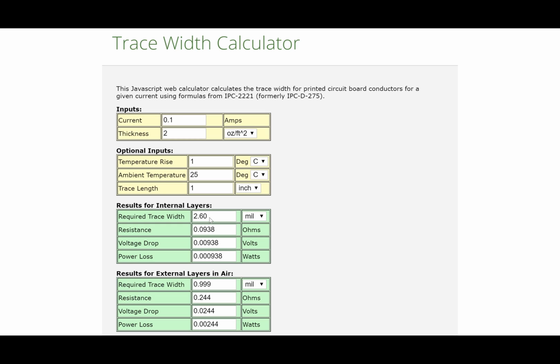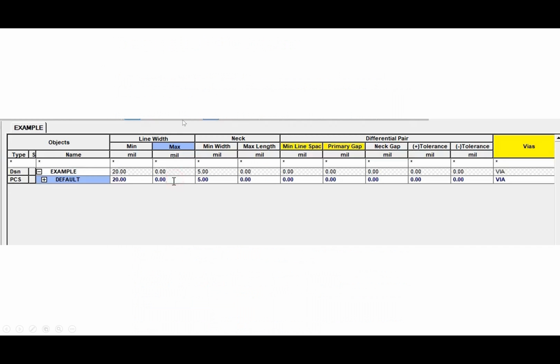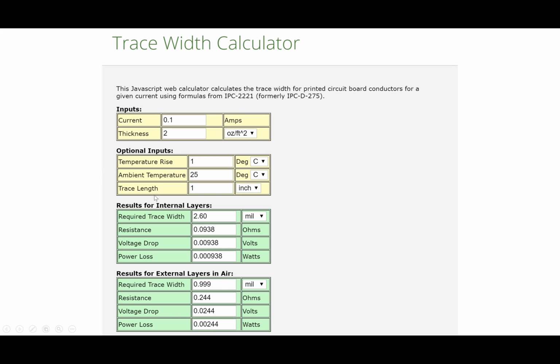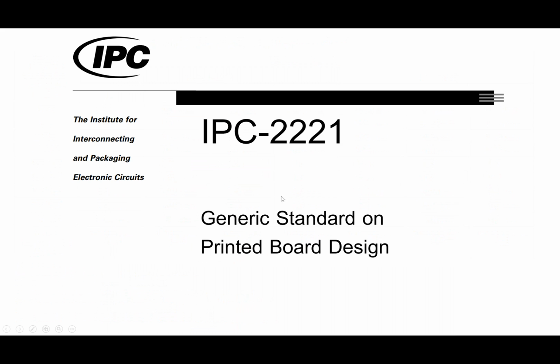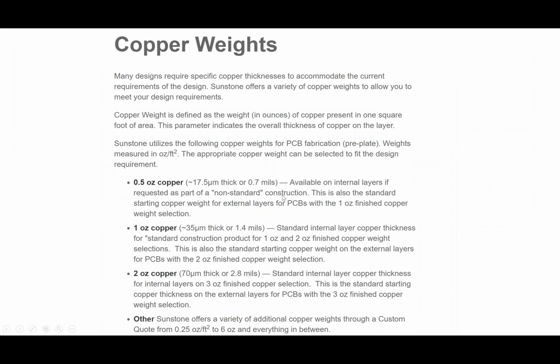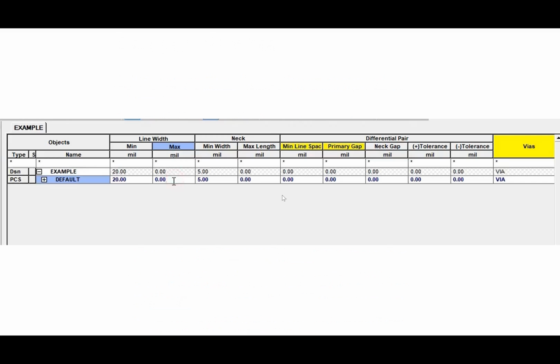His circuit is a power circuit. And typically if it's a power circuit, then we know the currents are going to be higher, and typically they're going to be thicker traces. So how we set these things in here ultimately gets decided by going through calculations like this, which are laid out in industry standards. Okay? So there's a lot for you guys to learn and to go through as we go through the semester, but those are some key basic concepts.